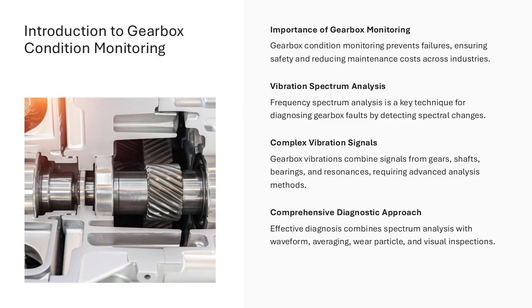Best practice requires correlation with time waveform analysis, time synchronous averaging, TSA, wear particle analysis, and, when possible, visual inspection. The material presented follows established condition monitoring principles used by vibration analysts and reliability engineers. The objective is to equip engineers with practical guidelines for interpreting spectral changes associated with common gearbox problems, understanding the physical forces behind those changes, and applying this knowledge in real-world machinery diagnostics.